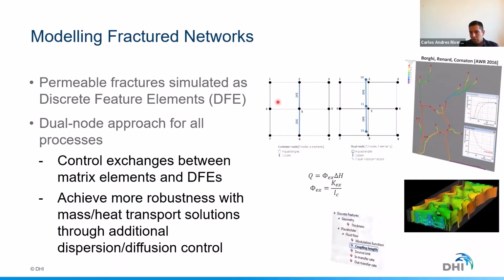It happens that we need to isolate these fractures, so the worst case or the extreme case will be a second porosity system. So we brought in the last version of the software the approach of the dual node connector, where basically you separate your fracture from the matrix that you're solving, no? And this separation is done by a 1D connector.